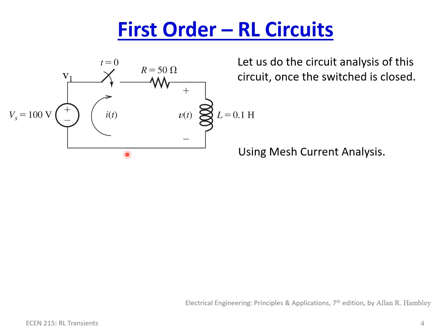By doing that, we're going to use mesh current analysis instead of the nodal voltage method. The reason why is we're using this I of t as this nice loop current, and we can simply apply the voltages across the different elements and sum them up. It becomes a much easier analysis because of the nature of the inductor. So in this case, instead of writing a KCL equation, we're going to be writing the KVL, the Kirchhoff's voltage law equation.